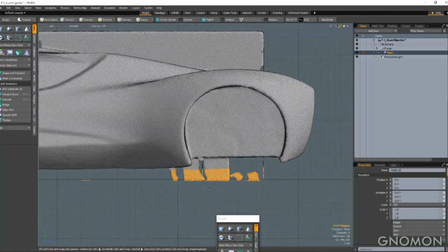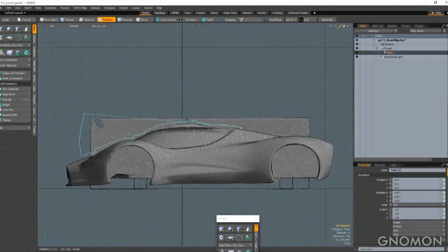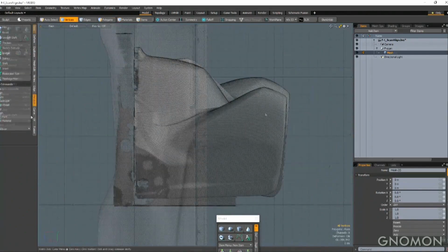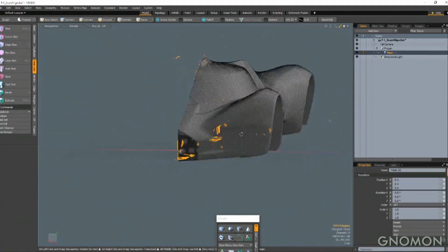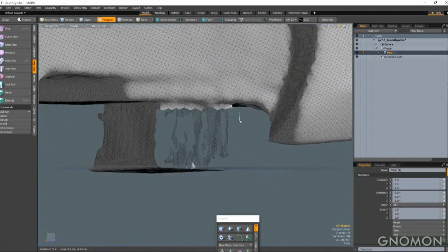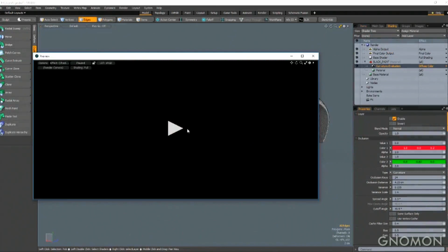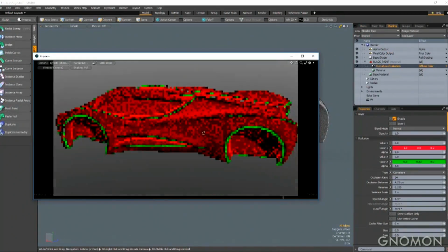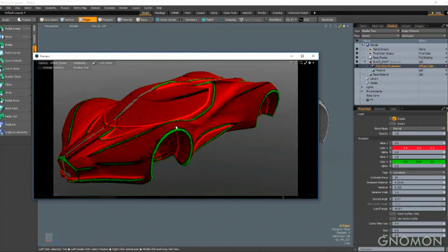This data usually is not exactly at the 0 location or world space. I did have an extreme example that was upside down and backwards in the middle of nowhere. So being able to plant it on the ground with hardly any effort, using the polygon tools and the retopology tools, clean it up, and then quickly look at the exterior surfaces. Are the corners too sharp? Are they too bulbous? Usually when a scale gets blown up, all those fillets get redone anyhow.